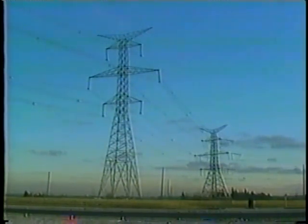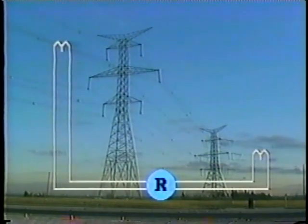Although the differential relay gives excellent protection for generators, transformers, and buses, it is not really suitable for feeder and transmission line protection. This is because the CTs would need to be located at either end of the line and the secondary leads conducted over a relatively long distance. This is expensive, and more important, the impedance of the secondary conductors could give rise to serious inaccuracies. As we shall see in future tapes, the differential principle is used for special applications.